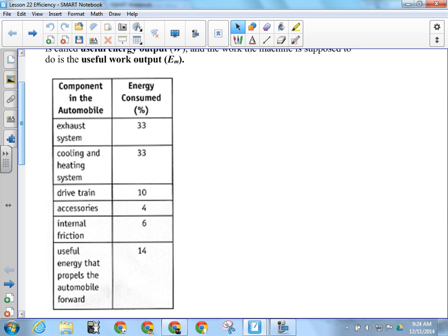So in a hybrid vehicle, what you have is two motors. A hybrid car is primarily a gasoline-powered vehicle. The electric motor only kicks in under load. If you're going uphill, the electric motor will kick in and assist the gas engine going up the hill. When you're pulling away from a stoplight and accelerating, and the engine has to work harder, that's when the electric motor kicks in. When you're driving on the highway, maintaining a constant speed on a flat stretch of road, your car is running entirely on gasoline.